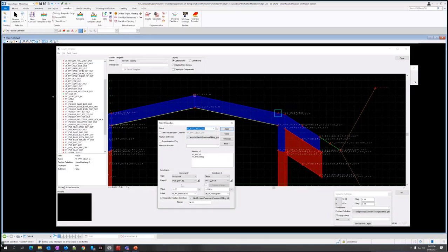We want to change the constraint on the horizontal to 5 feet. And then this constraint here, we're going to change. So it's set to a slope. It's going to depend on your project, how you need your milling resurfacing to behave. So in this case, we're actually just going to do a projected surface. So instead of saying it's just a 2% slope, it's just basically matching existing here.